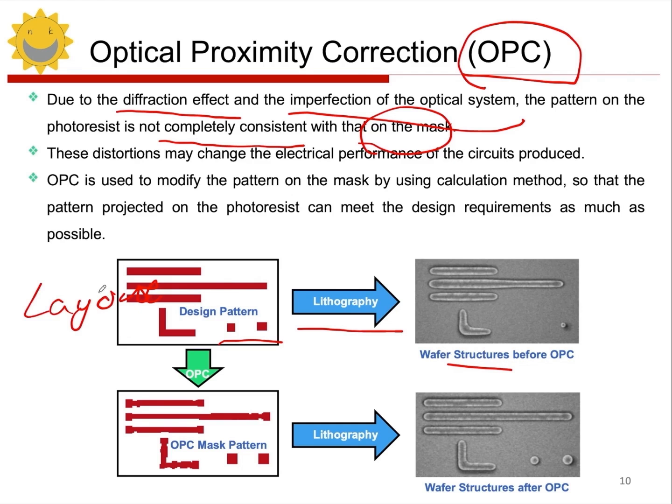In job view, patterns undergo OPC, so while shapes resemble the design, variations in flatness or width may occur. These changes are OPC's necessary adjustments, not data issues, ensuring the final pattern aligns with the design intent. Without OPC, significant output losses could occur.